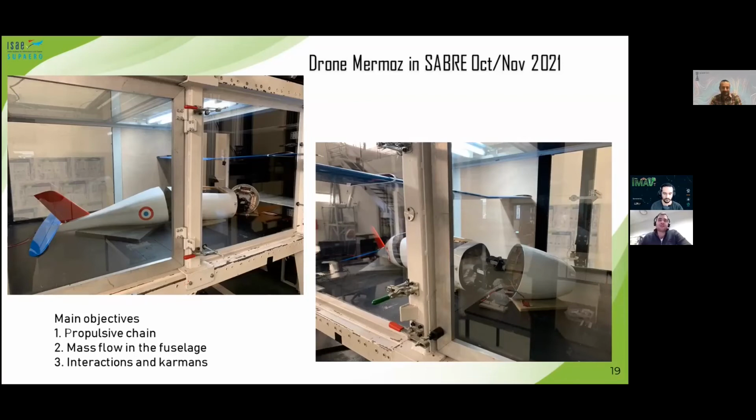So we have 3D printed fairings, and also modeled them from a special paste called plasticine. You maybe know it, kids play with that. We also managed to measure the benefit of having a wing junction of around 3% of the total drag in the wind tunnel case.